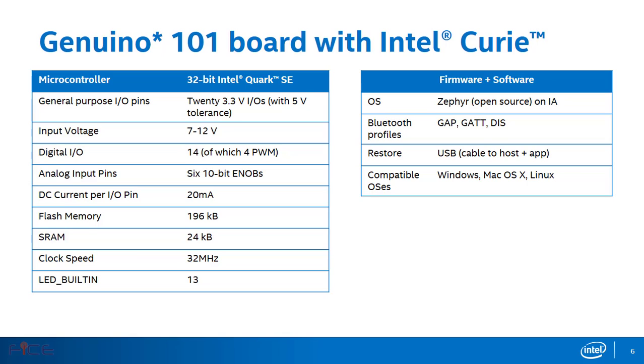It features a 32-bit DSP sensor hub with 128 neural network nodes, which has 2 pattern recognition algorithms. One is k-nearest neighbor and the second one is radial basis function. In addition to this, it has also got 2 distance matching formulas, LSUP and L1, and constant recognition time, which makes it unique from all other boards.